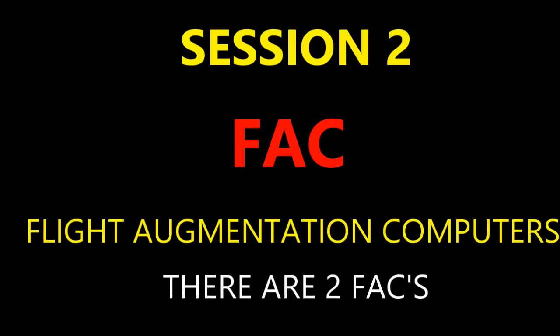And with the rudder travel limitation system, if you have a fault there, anything that's system related, a system failure, the master caution light's going to come on. That's a simple way to remember it. All right, and some other things to be aware of. I know I mentioned system failure, master caution is going to come on, and again, that could be the yaw damper system as well.